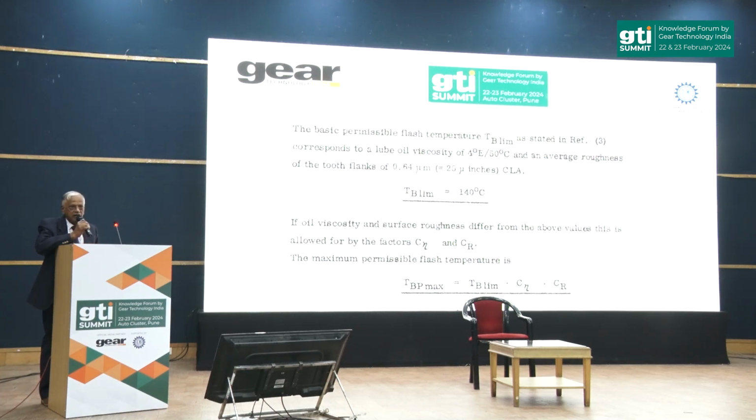Because, like Mahindran said, at that time there will be a temporary welding of the tooth flank due to temperature. So we have to see how to avoid that only by increasing the flash temperature of the oil. So we have to see how the flash temperature of the oil should be in design, and in those high-speed gears, more than 80 meters per second.